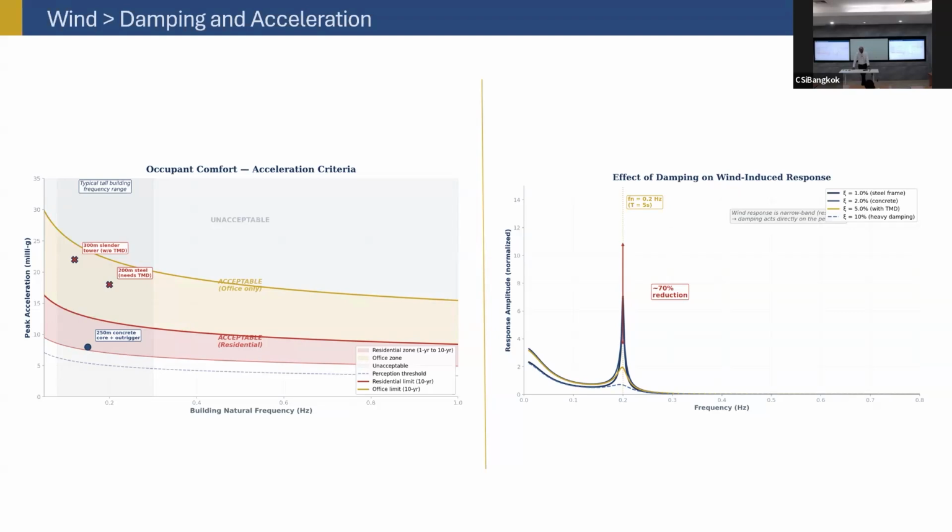Very, very challenging to do. Many buildings do not automatically qualify, especially tall ones. And the engineers get stuck with the design for acceleration control, not for strength, not for ductility, but acceleration. Strength and ductility are almost never tested, but acceleration is tested daily. So if you make a mistake on acceleration, people will start complaining right away.